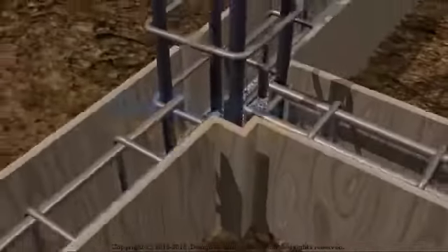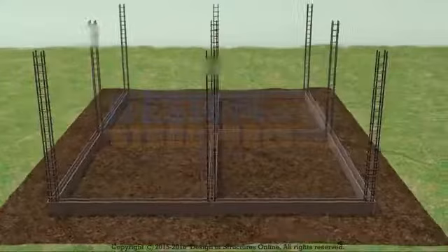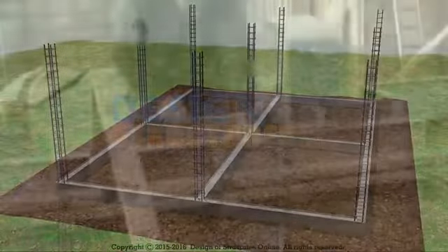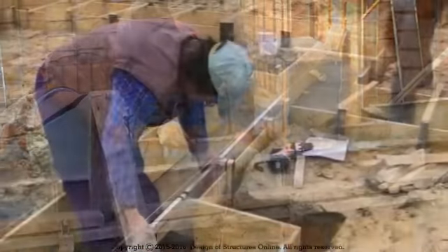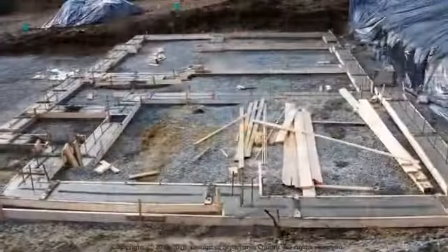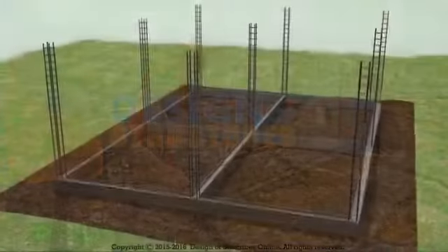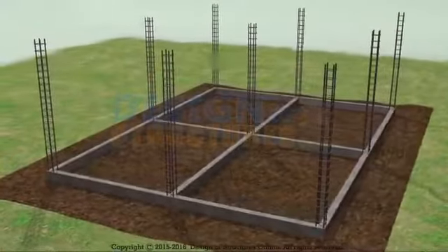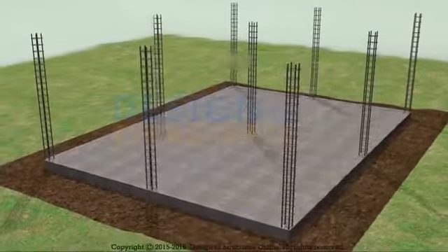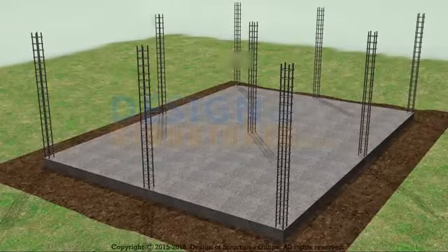Beam concreting. Beam is poured with concrete with grade mentioned in the drawings. The positioning of reinforcement should be properly aligned. Shuttering parts and connections should be arranged in a way that makes formwork removal easy and simple, prevents damage to concrete and formwork panels so that they can be reused without extensive repair. Slab concreting. Grade slab requires no reinforcement as it is resting on ground strata itself. Top of plinth beams and grade slab should be at the same level.